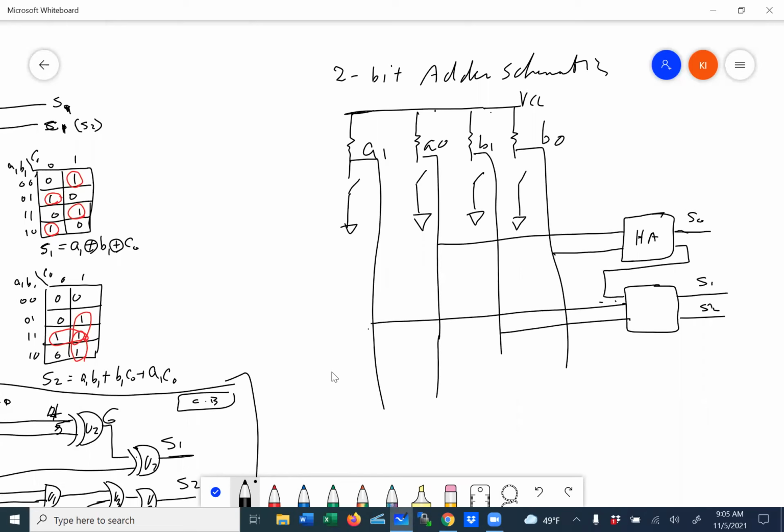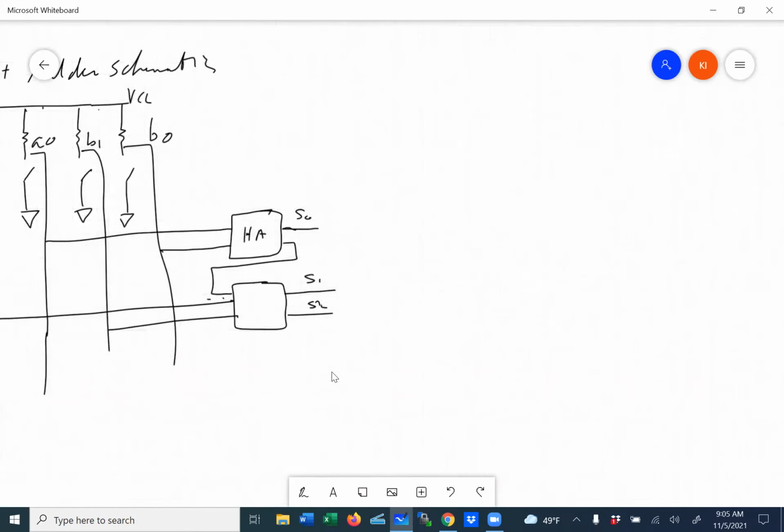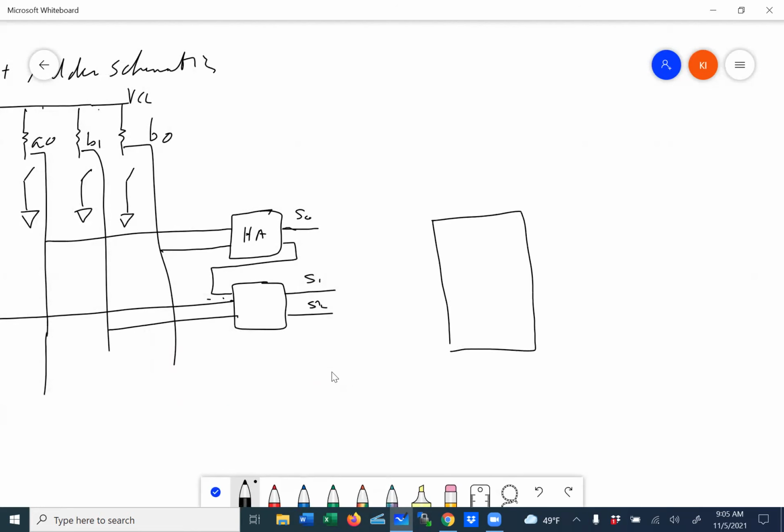Now we have a binary number, but we want to take that and display it on a 7-segment display. And in lab 4, before you got to this point, there was another experiment that showed you how to take a binary number and put it in, I forget, is it the 4511? Yes, it is, the 4511 HC chip.